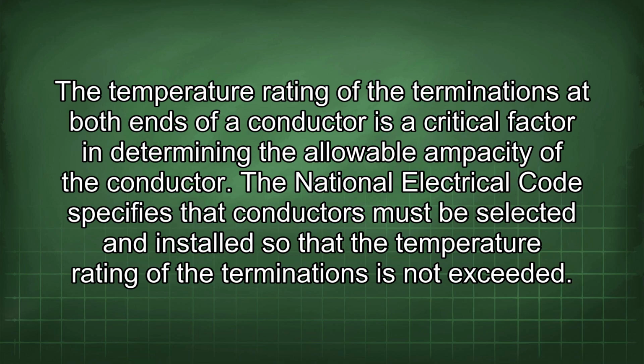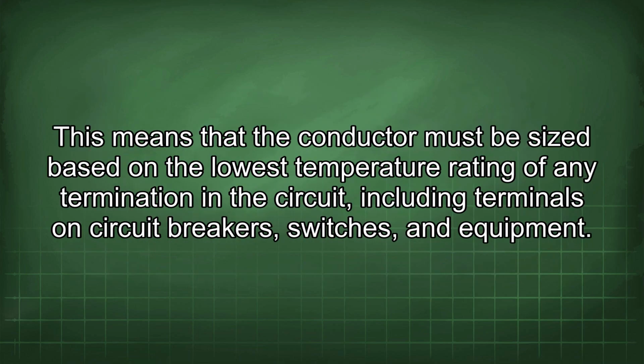Temperature rating of the terminations at both ends of a conductor is a critical factor in determining the allowable ampacity of the conductor. The National Electrical Code specifies that conductors must be selected and installed so that the temperature rating of the terminations is not exceeded. This means that the conductor must be sized based on the lowest temperature rating of any termination in the circuit, including terminals on circuit breakers, switches, and equipment.